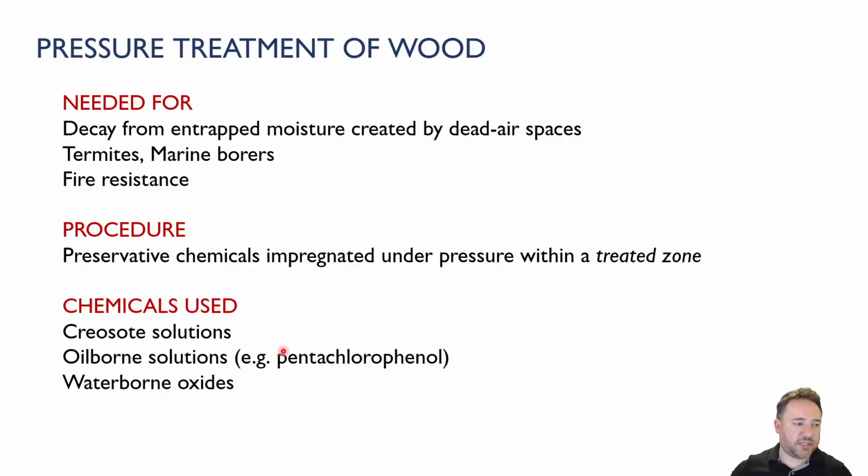Okay, so going back to pressure treatment, this is not our first line of defense. Usually, pressure treated wood is used for stuff that goes explicitly outside. Like if you're building a deck and you have that wood that looks kind of green, that's pressure treated wood. Now actually it looks a bit brown because it's a more environmentally friendly pressure treatment that they do. But basically, if we want to prevent insects, increase the fire resistance of the wood, and prevent fungal rot, we can use a pressure treatment to impregnate wood with chemicals to prevent those things from happening.